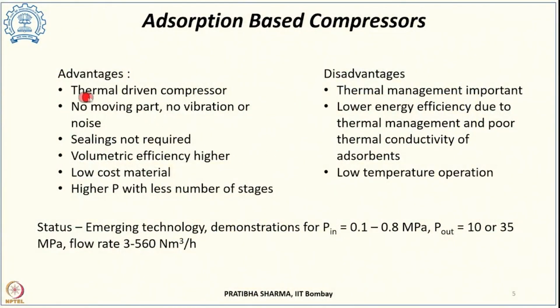If we look at the advantages of adsorption-based compressors, these are thermally driven devices, and even waste heat, like industrial waste heat, can be utilized for desorption. Since they do not have any moving parts, no vibration or noise is observed. We do not require sealings, as was required for electrochemical compressors.